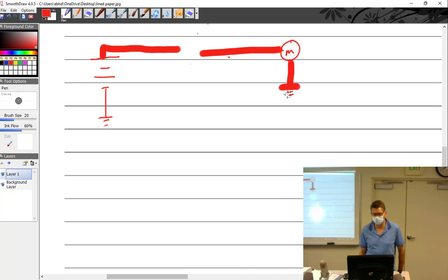Right? And that goes to a pretty big ground too. But I don't want this big old fat wire going from, how would it have to run? Like in my airplane, my battery's in the back. So I'd have to have a pretty big fat wire. It's about the size of my thumb. So it goes all the way up, and it would have to go from the battery up to my instrument panel, where I would have to have a switch the size of some sort of Frankenstein kind of, double contact, and then that wire would then go up to my starter, and that would work just fine.